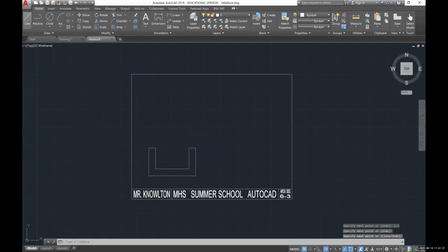There's 1 inch between views, so I'm going to go from here up 1 inch. And then I'm going to go 3.5 by 2. And we're going to go from here over 1 inch and up at a 45 degree.